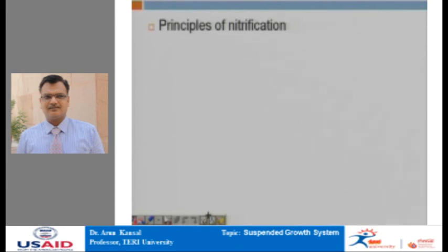Let me take you again from the fundamental concept, which we had discussed earlier in the context of sludge bulking: in the case of biological treatment, for each 100 units of BOD we require 5 units of nitrogen and approximately 1 unit of phosphorus if the process of treatment is aerobic. So, in the aerobic treatment process, the BOD to nitrogen to phosphorus ratio is 100:5:1.